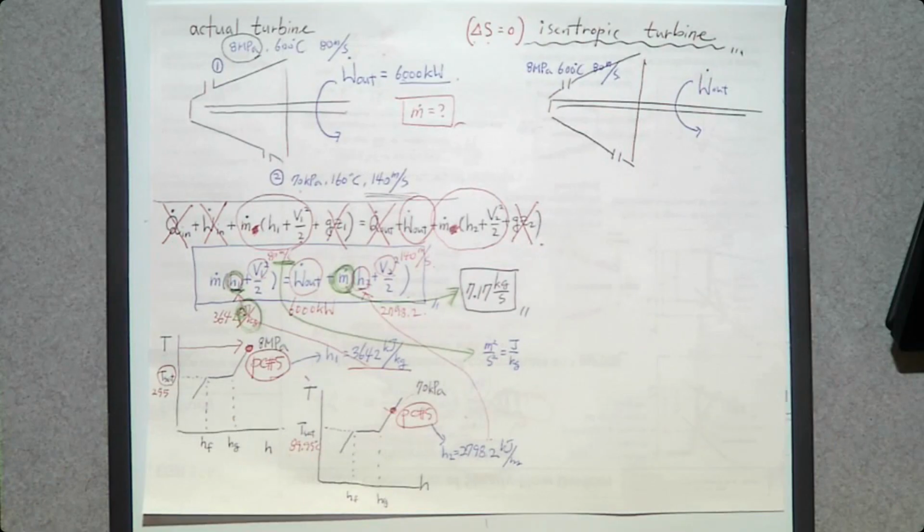70 kilopascal is the pressure in the pipe connected to the exit of this turbine. So that pressure should be based on whatever the pipe, the device, is connected to. The pressure at the exit does not depend on whatever happens inside. It depends on how this is connected.